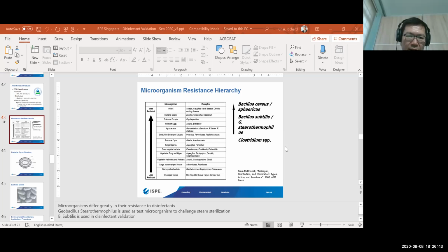Typically this can be 3 to 4 times or 5 times. There's no requirement on how many times, but typically it's at least between 3 to 5 times of cleaning. After each cleaning using the disinfectants, for example, you use disinfectants to clean for the first 3 days, and then after that, you use the sporicide agent. After each cleaning, you will monitor the count again.